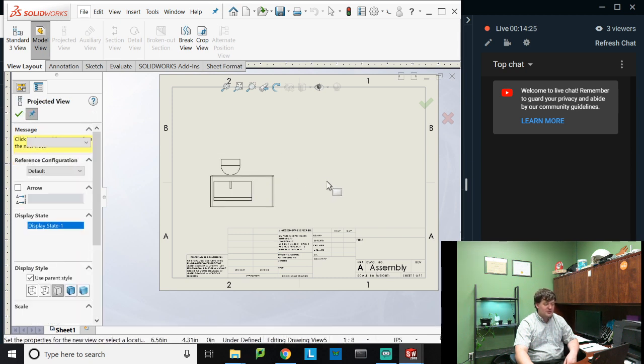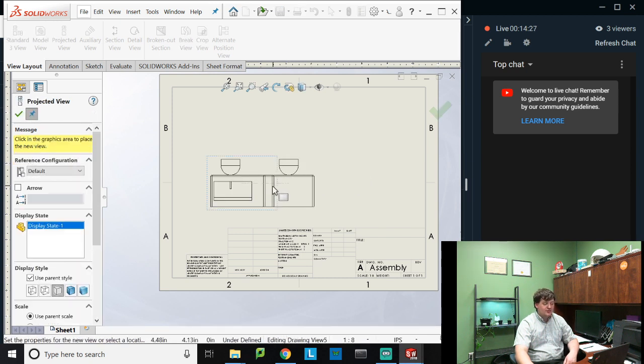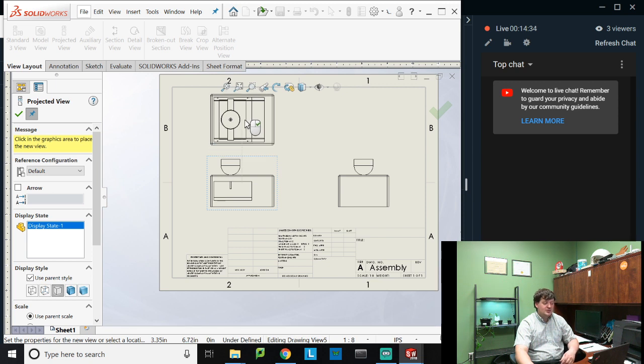A professional design of a part or an assembly features a front view, a side view that is aligned with it, and a top view that is aligned with it. You can see this line that's showing up right here; that is the alignment. You'll notice all my lines line up. If I were to trace a line from here to show where the bowl is, it would connect with the edge of the bowl there. The outside of the device here aligns with the outside of the device here. All of my lines align.